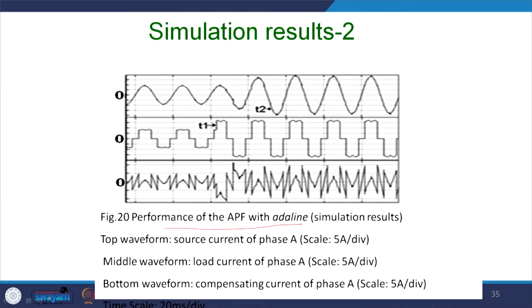So, this is the case of the simulations with the performance of the APF with Adaline, and what happened, you can see that the load change has been detected. It takes this much time to run, because it takes the data and tunes online, and ultimately this matches the values of the in phase component of the power P and Q, double checks it and gradually makes this voltage and current sinusoidal.